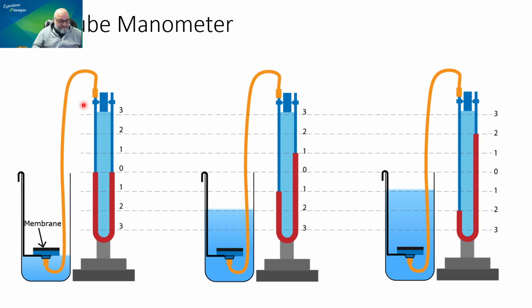Okay, so this is exactly why we need to talk about inches of water column. So here are 3 instances of the best manometer that have ever existed on Earth. The best manometer is the U-tube manometer. It does not need calibration because it is self-calibrated by gravity, for God's sake. And if you ask me, I will always use a U-tube manometer and never use a digital manometer.